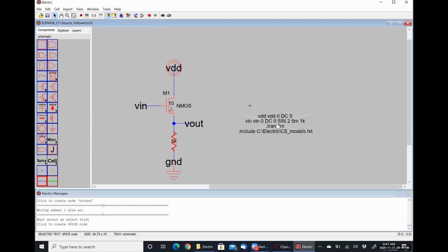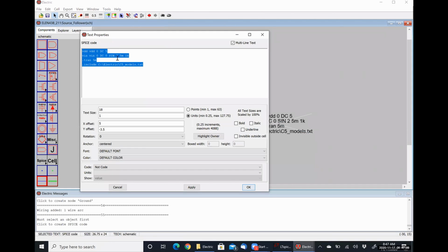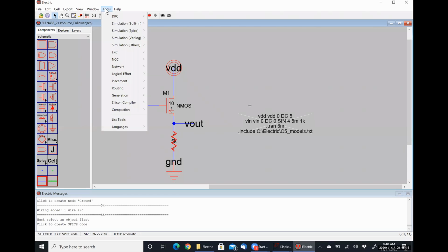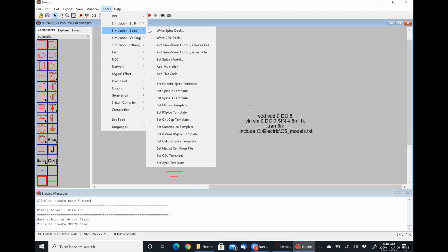And actually, instead of having a 2-volt offset, I'm going to call it a 4-volt offset because that's more in line with what the output of our differential amplifier has been. It has a 4-volt DC offset, and then it's usually somewhere on the order of a gain of 28. But let's run this and see what happens.